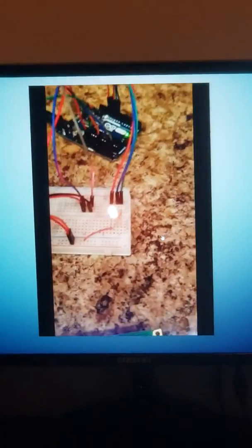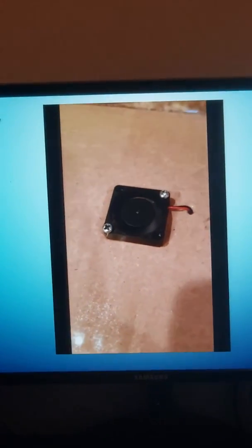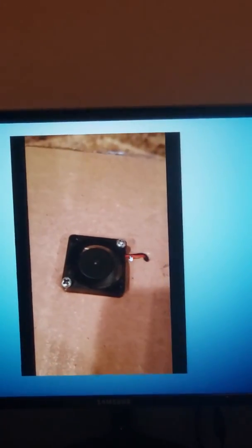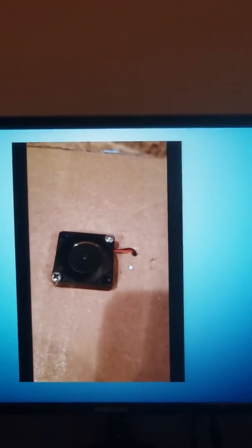We are in warning status, 92 degrees. The LED is orange. We hear a chirping sound from the speaker, and the fan is still blowing. Alright, I got it above. We are in alarm state. We have our warble, and the fan is still running.